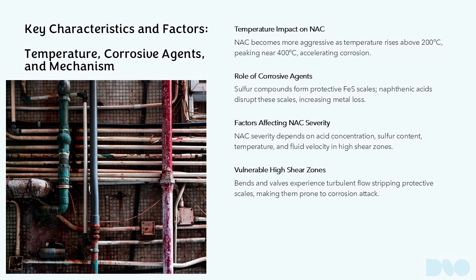to accelerated metal loss. The severity of NAC depends on several variables, including the concentration of naphthenic acids, measured by total acid number or TAN, sulfur content, operating temperature, and fluid velocity. High shear stress zones, such as bends and valves, are particularly vulnerable because turbulent flow can strip away protective scales, exposing fresh metal to corrosive attack. Understanding these factors is crucial for predicting corrosion behavior and implementing effective mitigation strategies.